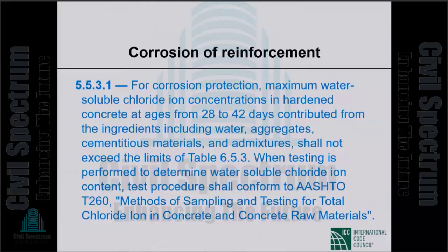Now we are going further, and this is extremely important. For corrosion protection, maximum water-soluble chloride ion concentrations in hardened concrete at ages from 28 to 42 days, contributed from the ingredients including water, aggregates, cementitious materials, and admixtures, shall not exceed the limits given.